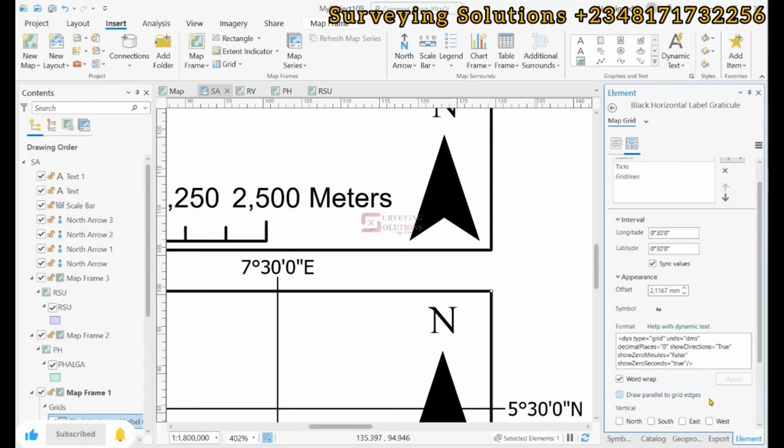So this means that this particular script here can be modified, right? Good. So maybe we'll make a video on how to change it from this DMS to northings and eastings. But for the purpose of this study area map, let's just stick with this. So we have the DMS in degrees, minutes, and seconds. We come up again, and we can decide to zoom to page.